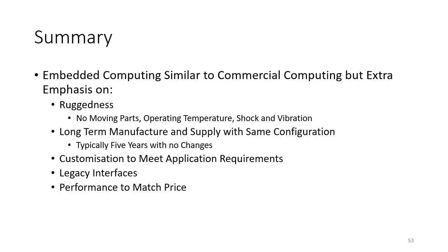And you need performance to match price. Of course, with embedded computing, you may get slightly lower performance than an equivalent commercial one at a higher price. So you've got to think about the long-term cost of ownership, and you've got to think about your current and future requirements. But ultimately, you want to spend the amount of money that you need to match the performance that you require. So particularly, for example, with an embedded gateway, if you're only transferring a few values, you don't need a very high-powered computer to do that. So it's helpful if you have a look at various embedded computing devices which have the required level of performance at a relatively low price, so you're not over-specifying what you do.